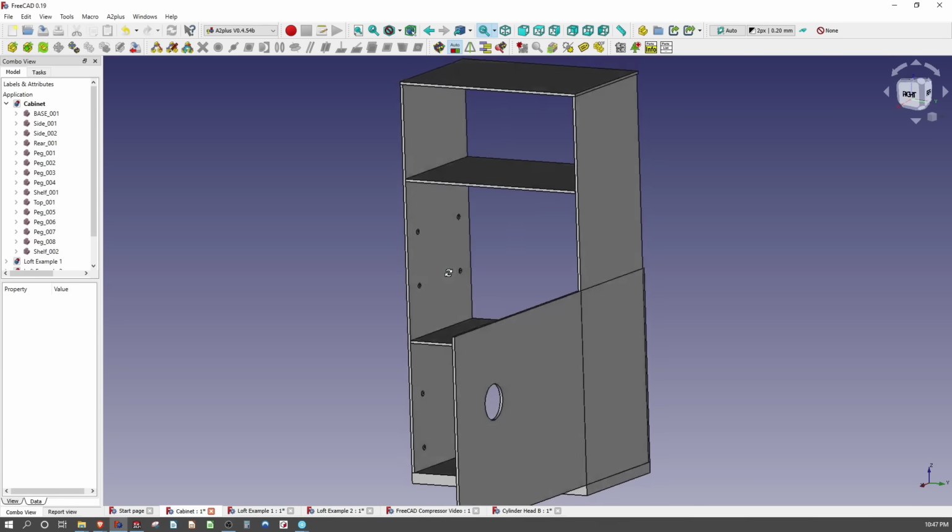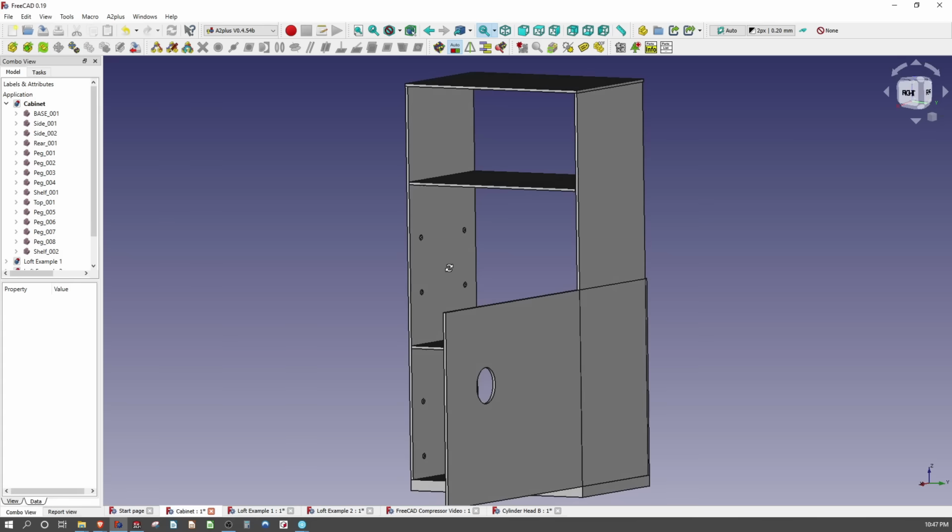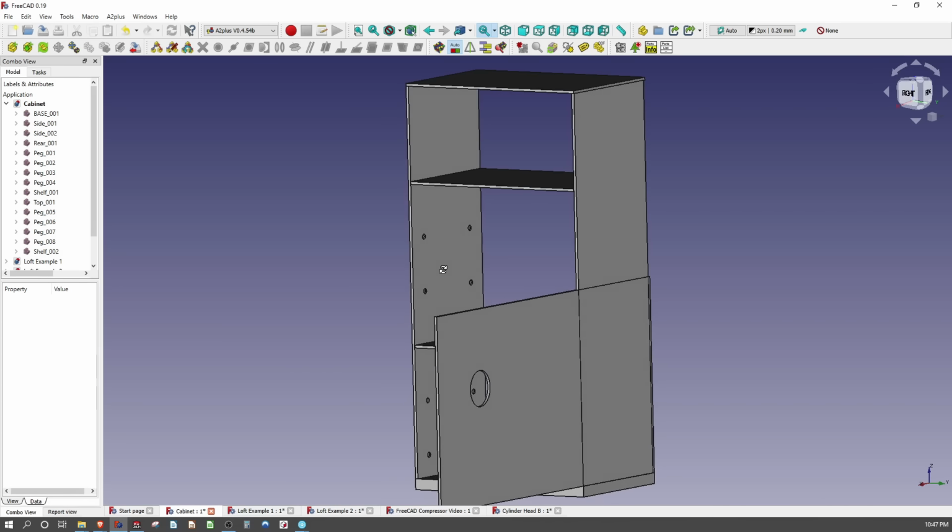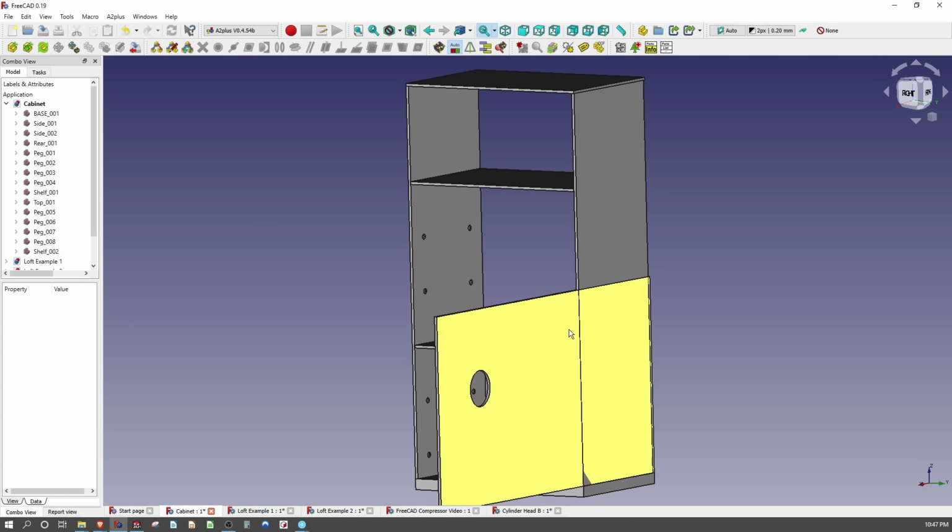Now this problem has been solved in the A3 and A4 workbenches. I haven't really touched A4. I know that A3 has occasional problems with redundant constraints. So with A3 you have to spend a lot of time thinking about how to add constraints so that they're not redundant. So there are some problems with FreeCAD assemblies just being a mixed bag. But with every new version of FreeCAD, it amazes me, so I'm sure that these things are being worked through.